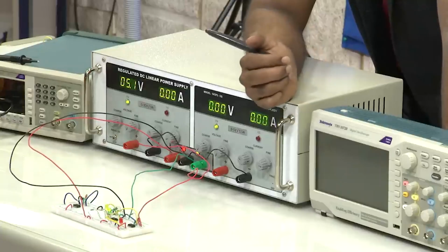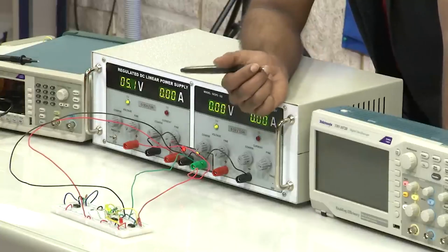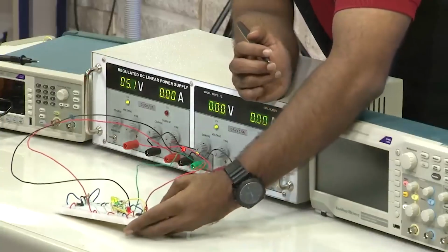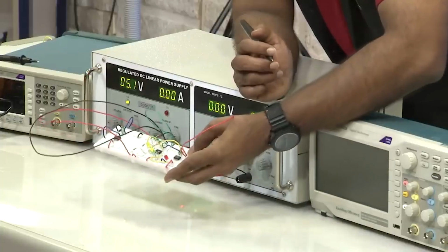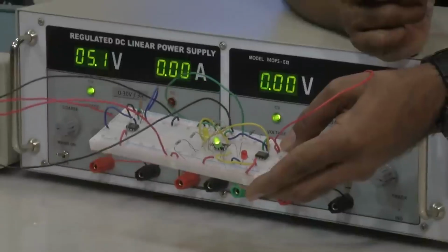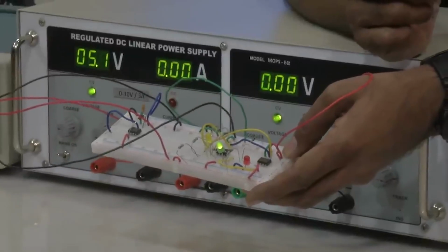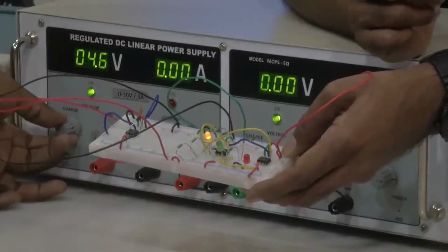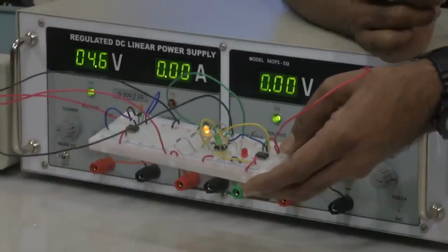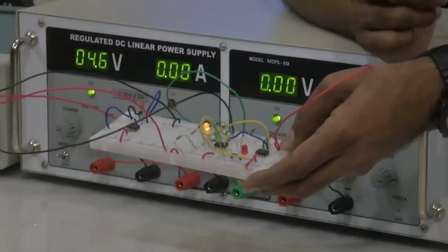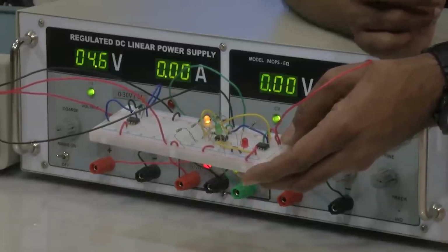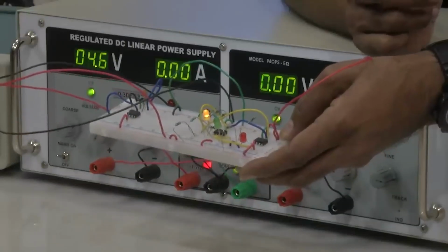Okay. So I can hold this circuit in my hand, so that you can also see the LED glowing along with the voltage. Now reduce it back to 4 volts please. You can see as soon as it is less than 5, we can see the first LED glowing, right. So this is exactly the comparator comparing the window between which it has to go high.